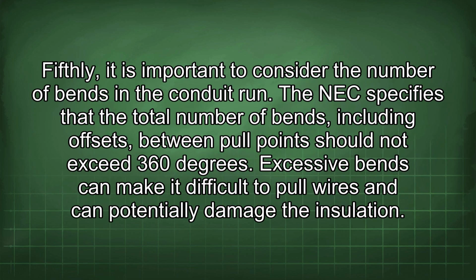Fifthly, it is important to consider the number of bends in the conduit run. The NEC specifies that the total number of bends, including offsets, between pull points should not exceed 360 degrees. Excessive bends can make it difficult to pull wires and can potentially damage the insulation.